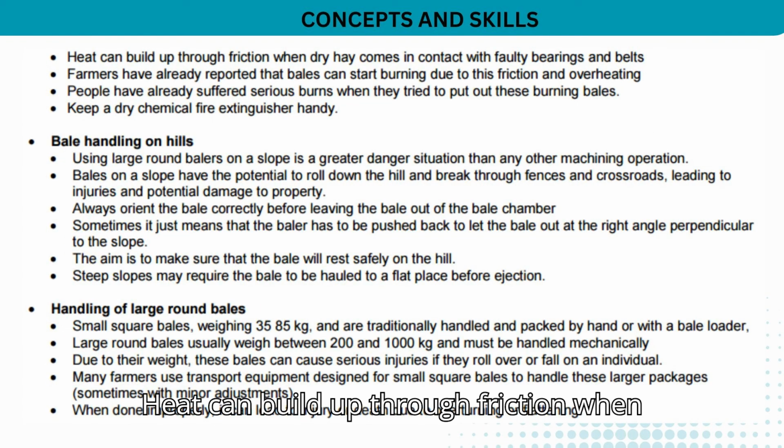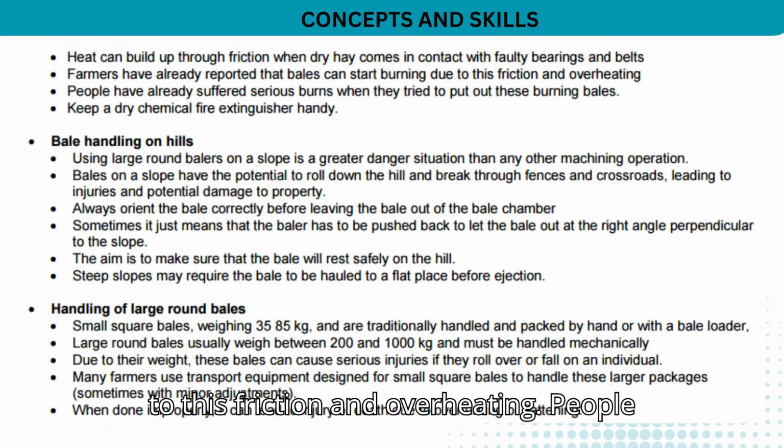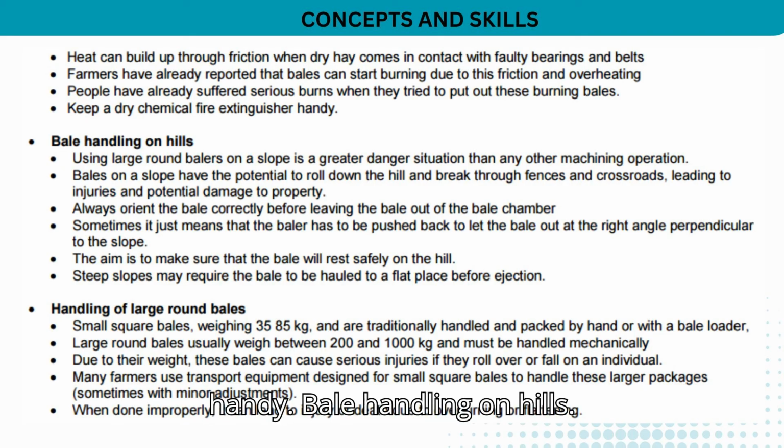Heat can build up through friction when dry hay comes in contact with faulty bearings and belts. Farmers have already reported that bales can start burning due to this friction and overheating. People have already suffered serious burns when they tried to put out these burning bales. Keep a dry chemical fire extinguisher handy.